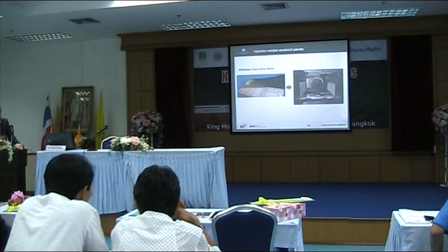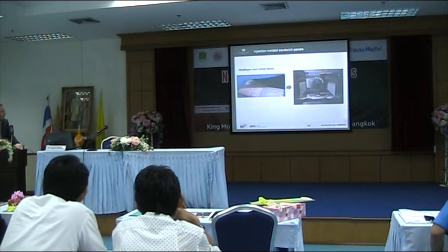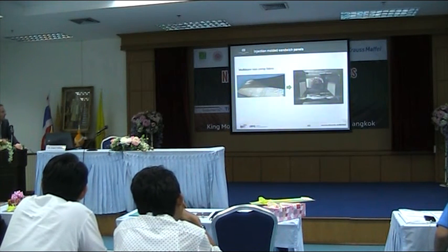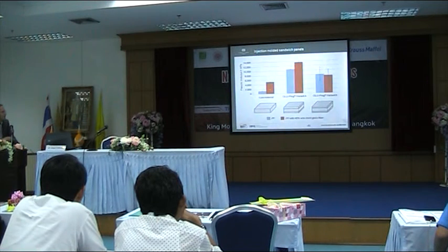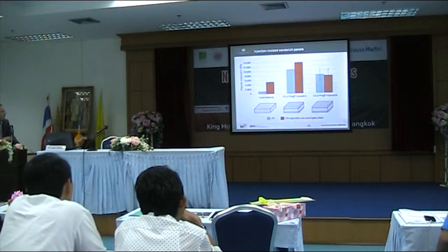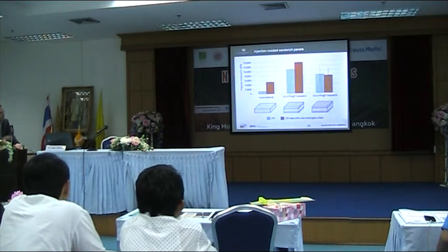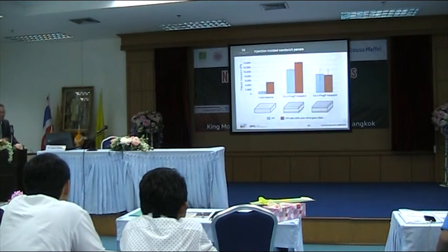You can also use it for the typical application of producing parts in the injection molding process. And here you have to get some property feeling. If you have the pure matrix system without reinforcement, you reach a flexural modulus with polypropylene of around 1,700 megapascal.